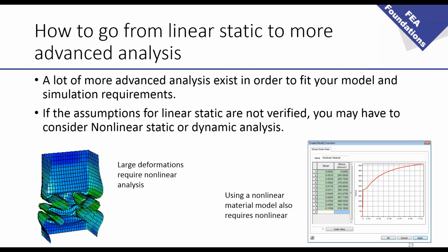Well, actually, a lot of more advanced analyses exist, and you have to know them. In order to analyze the model properly, you have to know what the assumptions are, and whether they are verified or not. If you check and you have large deformation, for example, then you know that you have to use nonlinear analysis. Or if you have a nonlinear material model, you know that you may have plastic deformation, and then you have to go to nonlinear analysis.